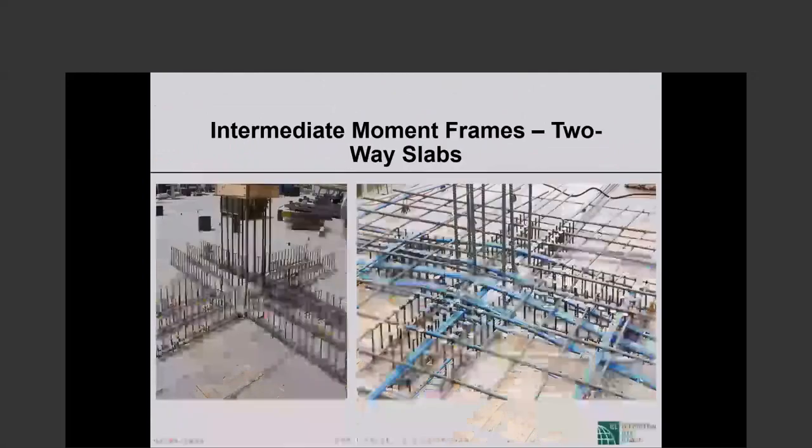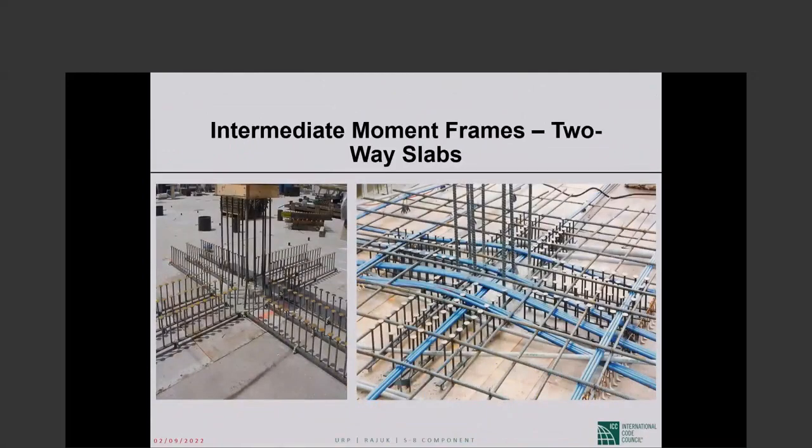Today, as I mentioned, pretty much the standard punching shear reinforcement are the stud rails. That's what everybody provides. And I know plenty of California engineers who will just throw this in. They don't try to figure out if they can get exemptions on this and that. This is cheap insurance.